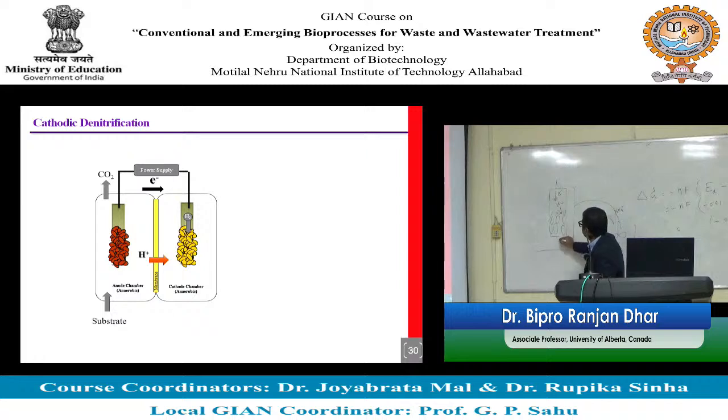So nitrate is the electron acceptor there, and you have an electron donor, and you have bacteria. So you have everything to get denitrification, right? And then the effluent can go back to your aeration tank for the next process. So in that effluent going back to the aeration tank, what is there? Oh, there is no nitrogen there. You completely remove it, right? So clean water.